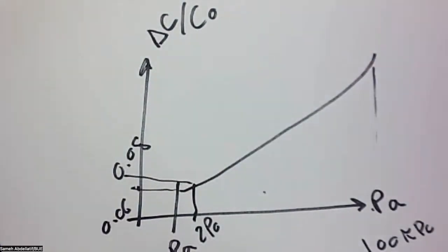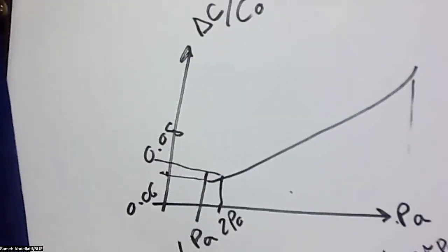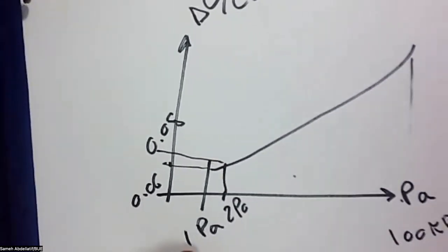However, take care, as this is not a linear sensing process, that means your sensitivity will change based on the range you are measuring. If you measure the sensitivity in a relatively high range, for example at 100K Pascal, you will find a different value. So first you plot that transfer function, then you determine the limit of sensing and the variation in the capacitance, which is the sensitivity, and then you start to propose an interfacing circuit.